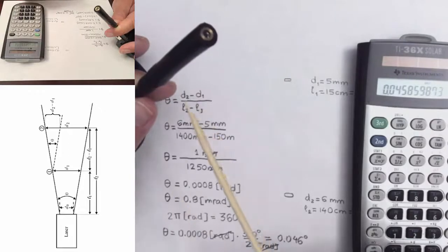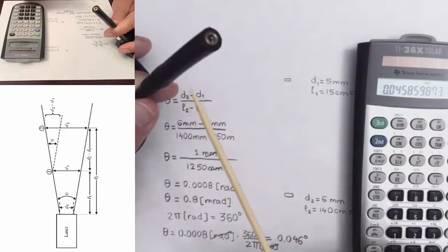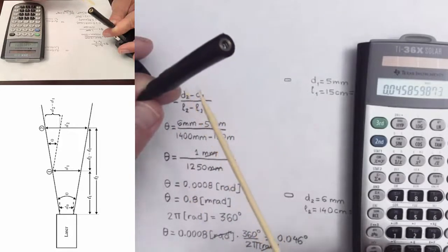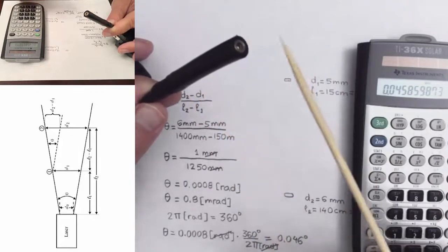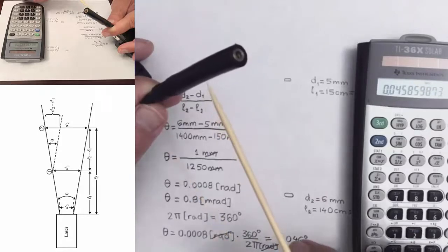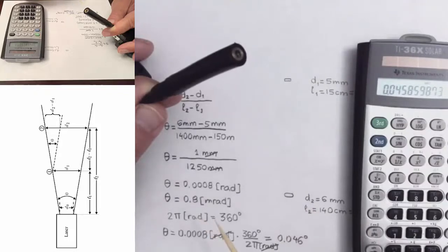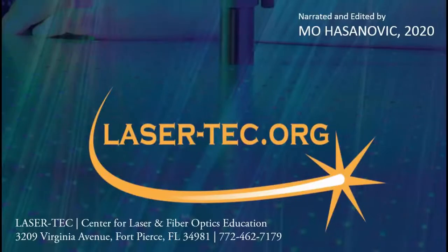Once more, a laser diode is characterized by a significant beam divergence of 20-30 degrees or more. However, in the case of our laser diode module, we don't have just the laser diode, but also a small lens that's collimating the beam, meaning reducing this significant divergence produced by the laser diode, so that whatever comes out of the aperture of the laser has a very small divergence, as we observed in our calculations.